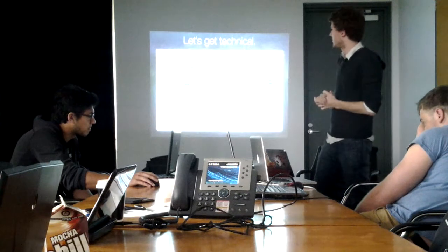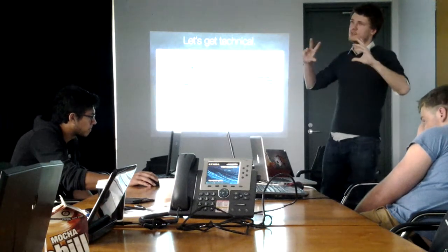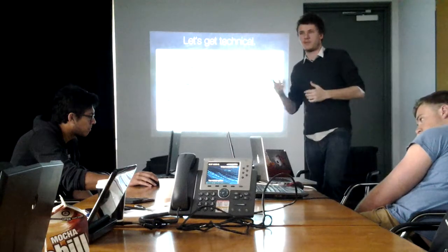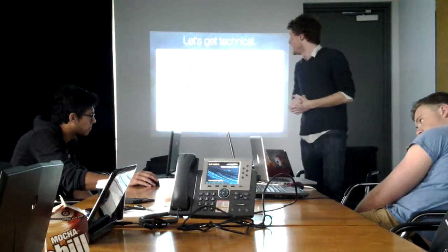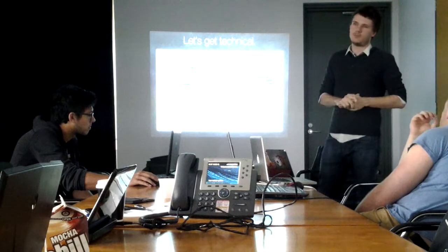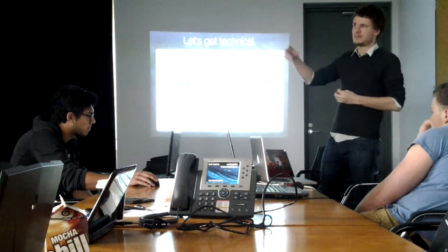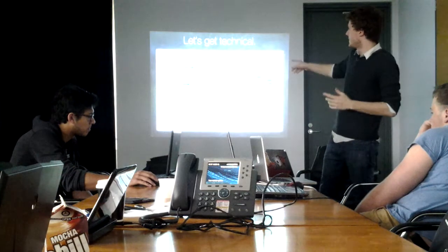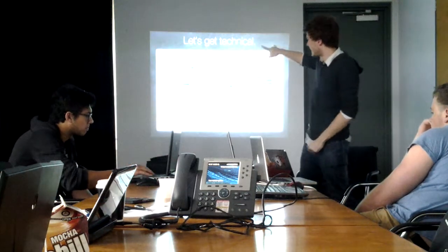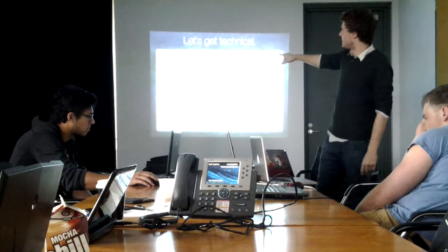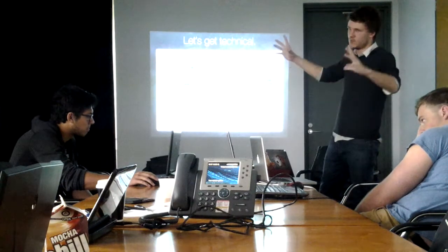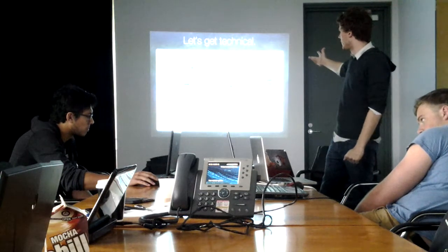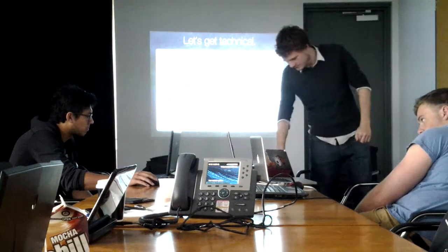Similarly, ungrib takes the grid data, because there are multiple different formats in which atmospheric data comes. Everyone has their own standards. So ungrib is the intermediate step in between taking all the different formats of data and turning it into a format that WPS and WRF will understand. MetGrid then combines your static GeoGrid data and your atmospheric data from ungrib into just one big file, and then it passes it to WRF, which then runs the simulation.